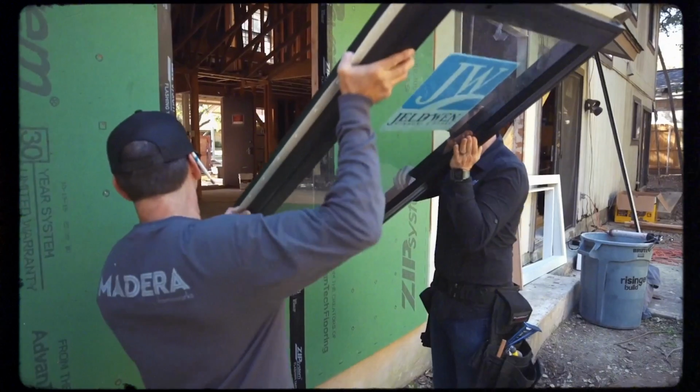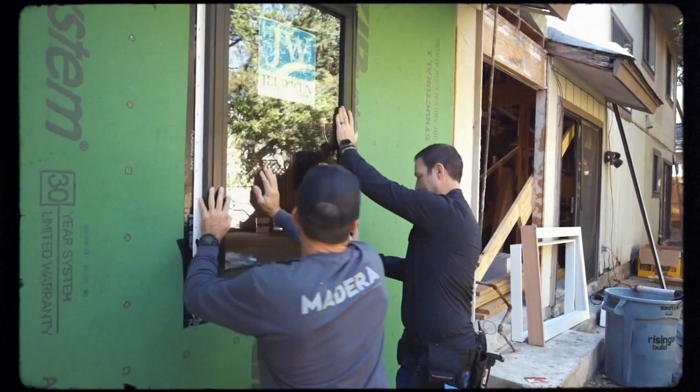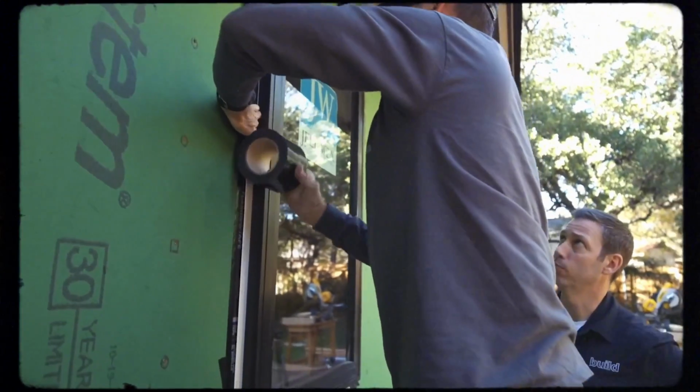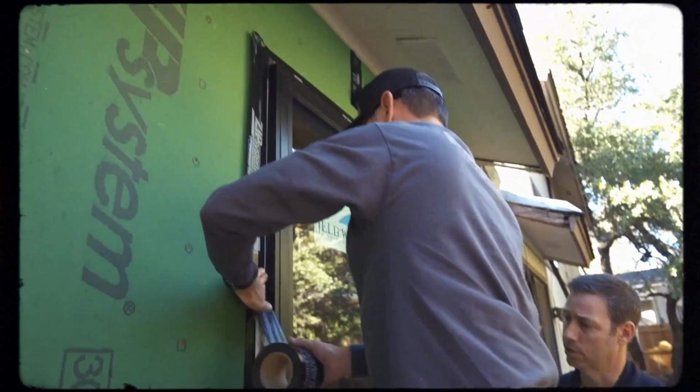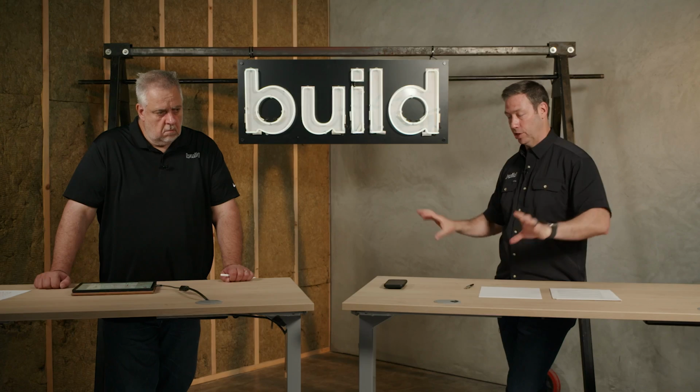Yeah, for sure. And I'm going to steal your thunder a little bit, but there's really two ways to install a window. There's the barrier method, and most American windows are flanged windows that have a flange to structurally install the window, and that's a flashing point that we'll use to stop the water from getting past the window. The barrier method basically means that when we install that window, we're flashing all the way around it, typically with some type of tape or sealant. And that is an approved method through AAMA, the American Architectural Manufacturers Association.